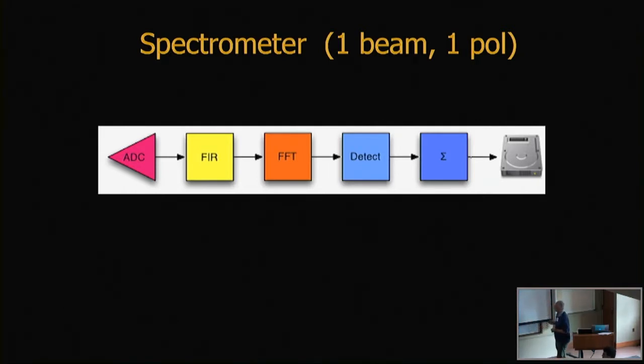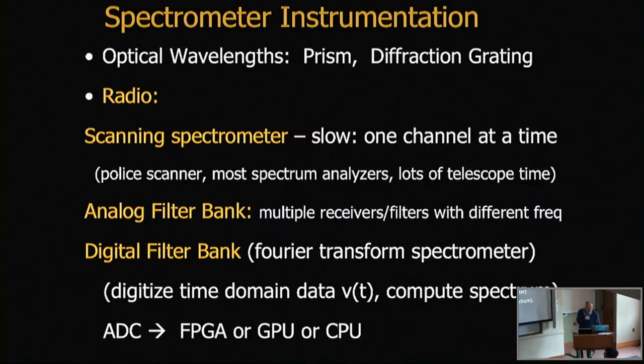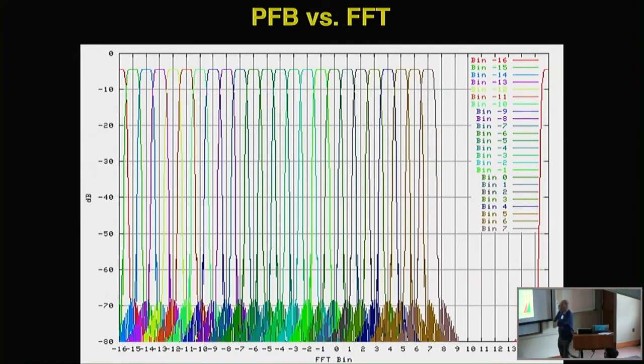I think so, but just go back to the PFB picture. What you're seeing there really is the response, not what you're measuring. It's what the instrument does: it puts a filter over the time domain signal, and the x-axis is frequency, and you're measuring how much power there is at every frequency by putting a little filter over the series. So each one of these things is a filter.